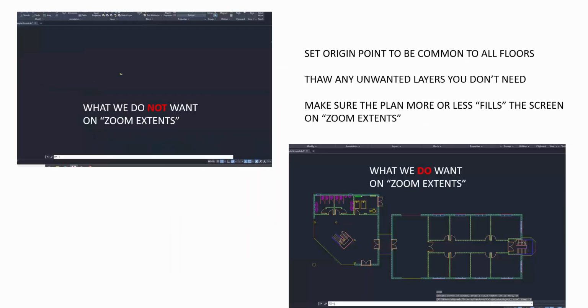The other consideration is the extents of the layout. You might find that an architect may use a site plan as an underlying layout on a frozen layer. That will affect the extents of the drawing. There is a limit of 1,000 times magnification in MEP Works, and you don't want to be hampered by not being able to zoom in because the source drawing still retains the extents, including the frozen layers.